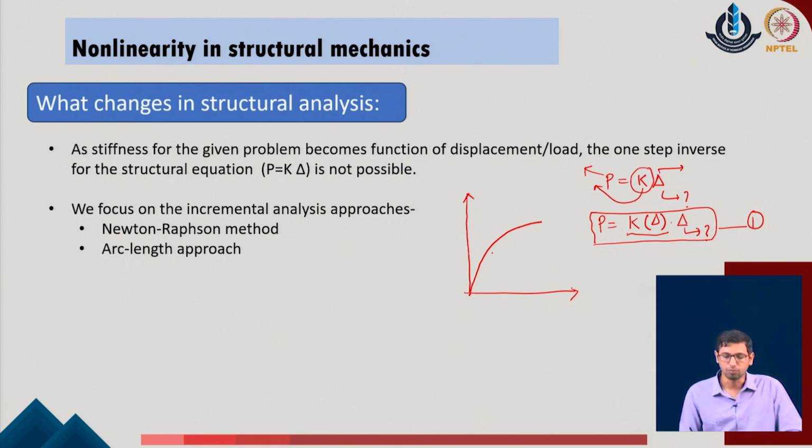But now in a nonlinear problem, as the value of the displacement in the given system is identified at a point and the corresponding value of the load is located, the stiffness relationship between these two values will not remain the same as we move to a different displacement of the given system. So, in order to know the response of the given system, the general analysis approaches typically rely upon tracking the given curve. We keep on moving to the different neighborhood points of the given system, keep on evaluating the new values of the stiffness coefficients at that particular point, and try to evaluate the response of the system at these successive points of the given system.